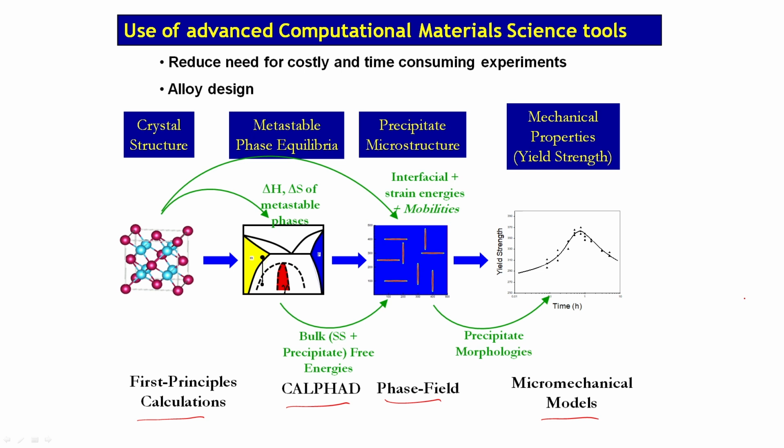as nanoscale systems. Now, CALPHAD provides you phases and their quantities in the microstructure, but it does not provide the real microstructure: how these phases are distributed, how they look, what their sizes, shapes, and morphologies are. It does not provide that, because it is a thermodynamic calculation. Secondly, it mostly provides the stable phases, the thermodynamically stable phases.